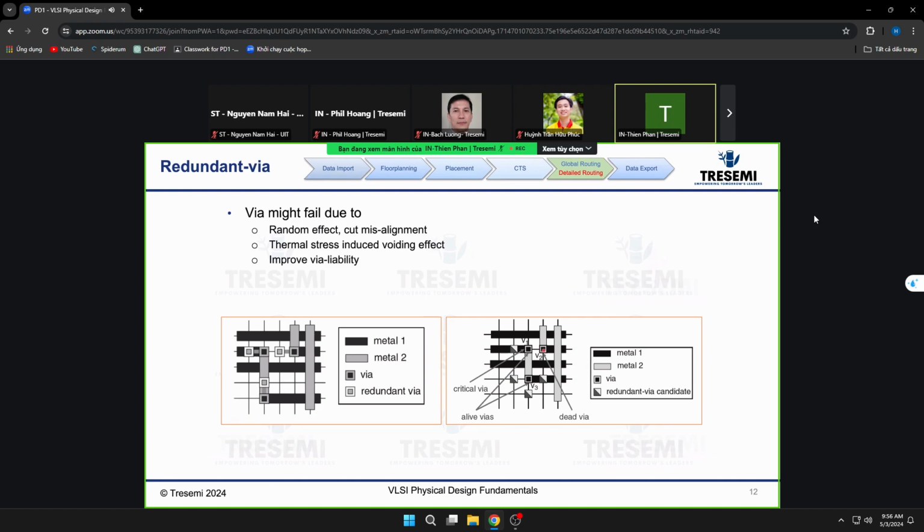the term used for it is a dead via, right? It's essentially there's no location next to it where we can add another additional via. So that's it. We have to leave it with a single via. We can't add more. And then V3, we have 3 different options: one, we have one option. Two, we have no option. And three, we have three different options, right?